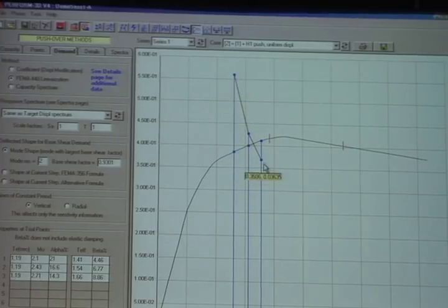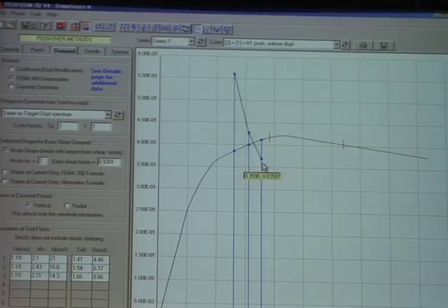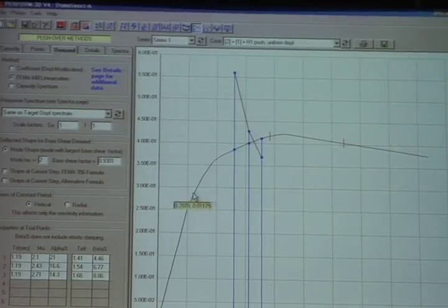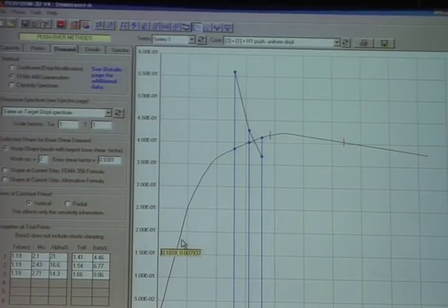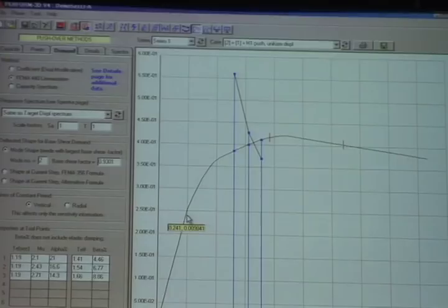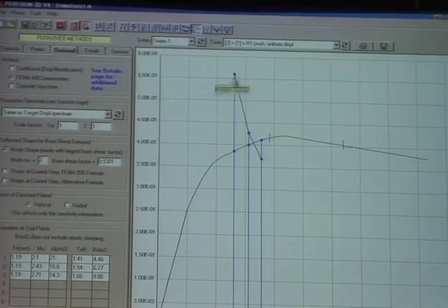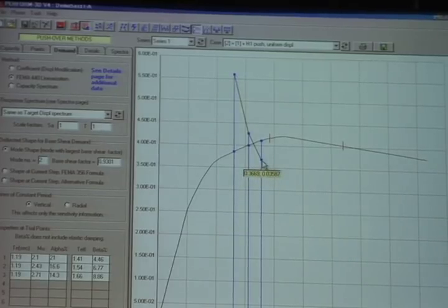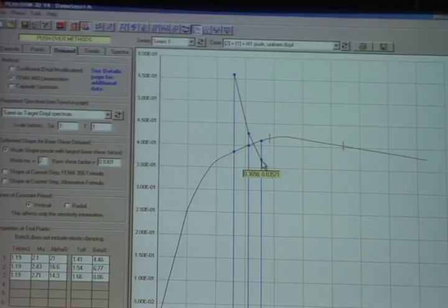Without going into too much detail, it tells you sensitivity information. What this says is that if you were to increase the stiffness and strength of this curve so as it came up here and passed through this point, so the same curve but with an increase in stiffness and strength in the same proportions, then this would be your target displacement. Correspondingly, if you were to reduce the stiffness and strength so as it passed through here, this would be your target displacement. It gives you some idea of what would happen, at least according to the pushover theory, if you were to vary the design.